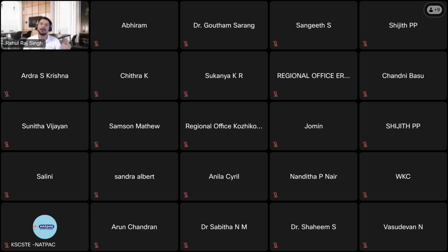The last step after we do all the calibration is, what is the impact of calibration? Impact here means, number one, what is the effect on pavement thicknesses? Number two, what are the critical distresses? It was failing in which particular distress? Was it bottom-up cracking, IRI, rutting? So that is the impact of calibration. We took 44 new pavement sections for flexible and 44 new pavement sections for rigid, designed them using AASHTO as well as the new calibrated models in Pavement ME, and found out the difference and also the critical design distresses.